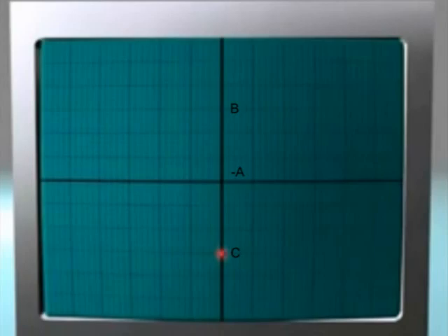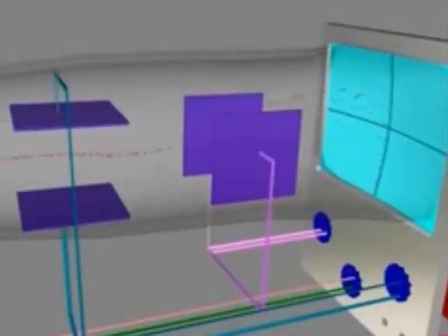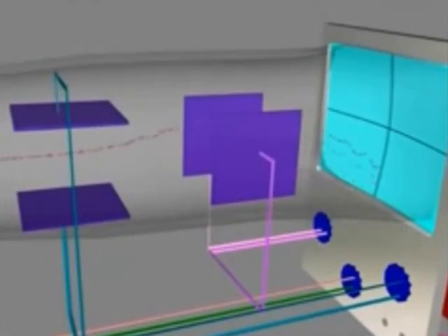If the reversals of the polarity are sustained, the spot will shift from B to C and back at a frequency of the reversals. With an alternating voltage, the spot moves up and down in accordance with the instantaneous voltage at the frequency of the AC.